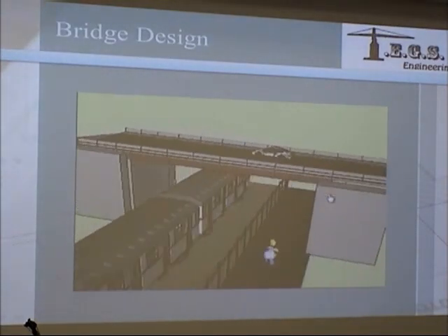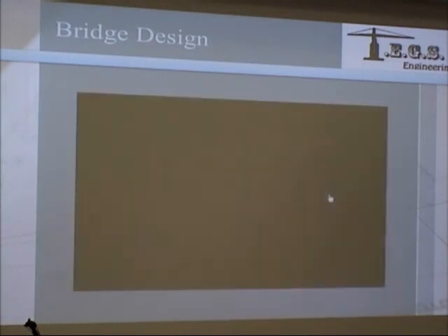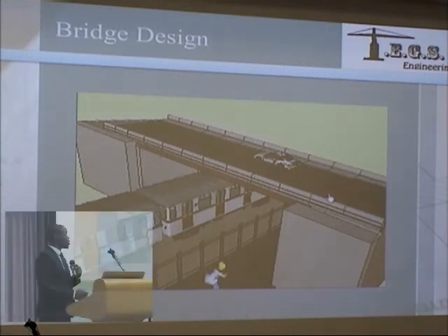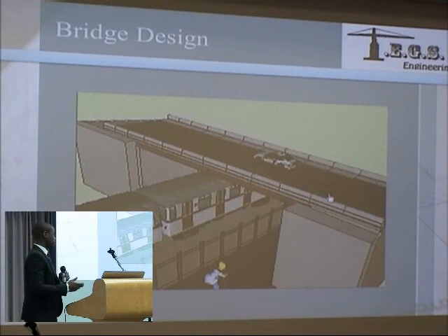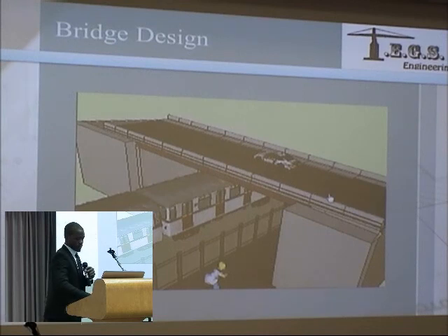Here's a 3D schematic of the bridge, showing all its components. The bridge is 42 feet long and 32 feet wide, and the span consists of two 12-foot lanes, one 5-foot sidewalk, and two parapet walls on each side. Beneath the bridge, there's a vertical and horizontal clearance of 26 feet and 40 feet for both the railway and the bike path.